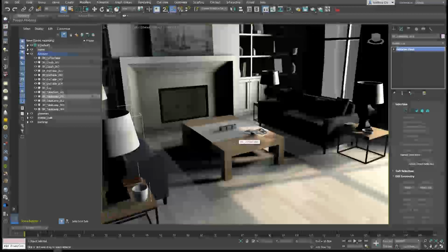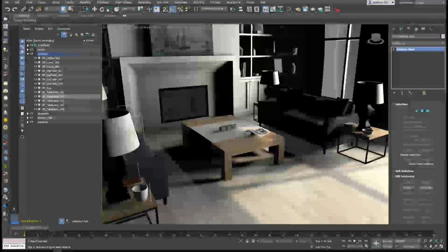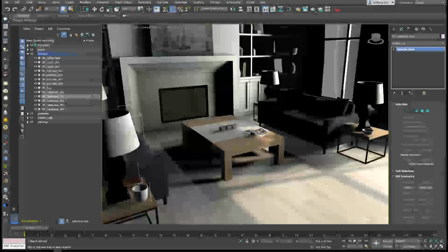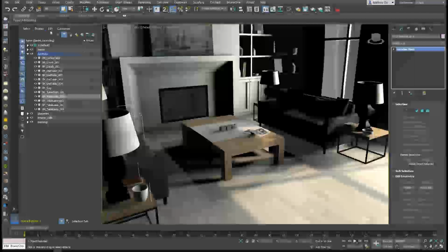It also converts textures and materials, adjusts the working unit scale and coordinate system, pivot points, scene hierarchy, and more, all automatically. And it automatically generates light map UVs if we need those. And obviously when we're going to render light maps, we do. And it can convert grayscale bump maps to normal maps for us automatically. So let's go ahead and see what that process looks like here.